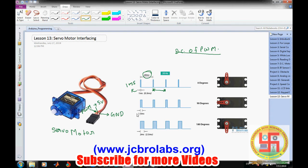Now if we change the pulse width of this PWM wave, we can change the angular motion of this motor. So let's say if we are applying 1.5 millisecond pulse with a 50 hertz frequency, the motor will rotate by 90 degree and it will stay there. It is not like it keeps on rotating, it will stay there. Similarly, if we apply a maximum, let's say 2 millisecond pulse, then it will rotate 180 degree. In some cases the maximum is 2.5 millisecond.